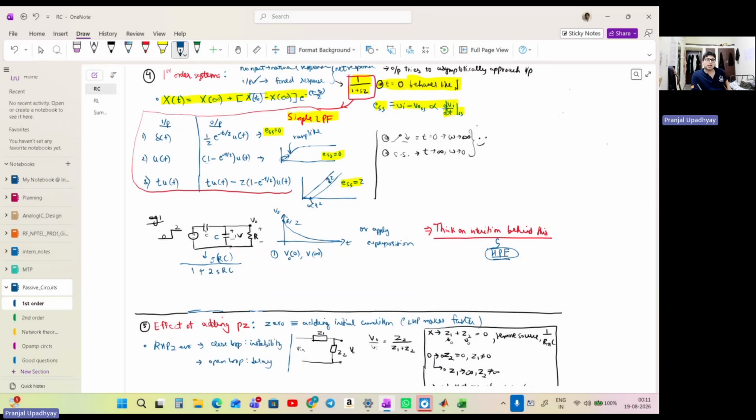You can understand that at zero, since this is a voltage source, by the way, this guy is open, and thus nothing will propagate over here. And at infinite, this guy will short, and this guy will short, and this guy is comparatively infinite as compared to a short, right? And so half the voltage of the input will appear here. So it's a high pass system. That is something we can understand. And from this also we can very intuitively and quickly sketch the transfer function.